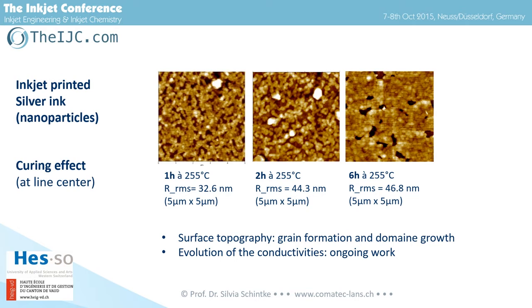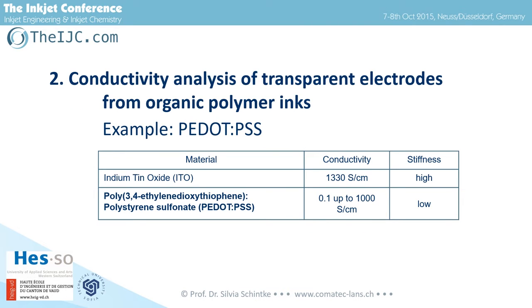So I want to come to conductivity measurements and how we perform them. We work mainly with organic thin films, and then the critical issue is really how to measure conductivity of very soft material. Already measuring conductivity is not an easy task, because normally you can come with 2 electrical probes. If you do it only with 2 electrical probes, you will have the resistance of your probe.